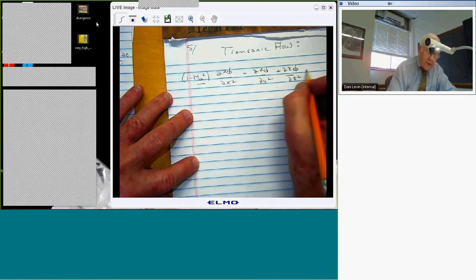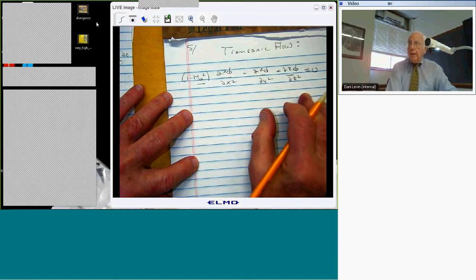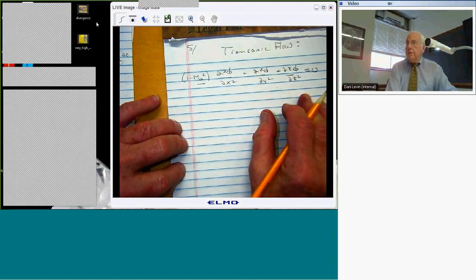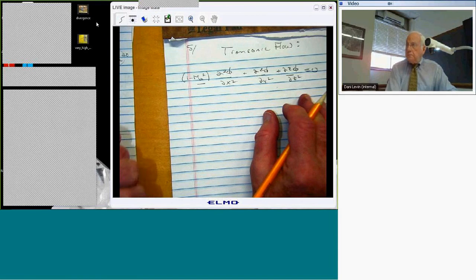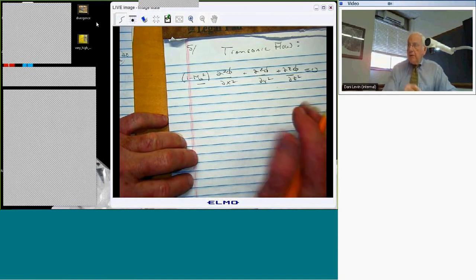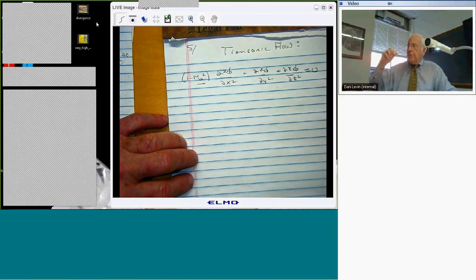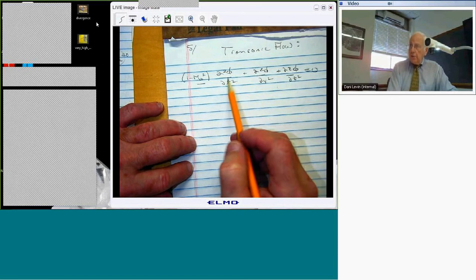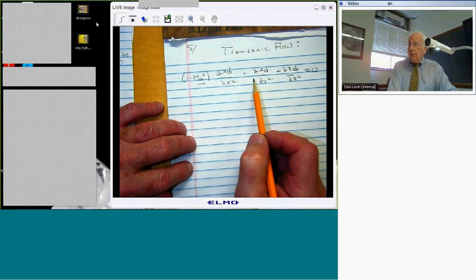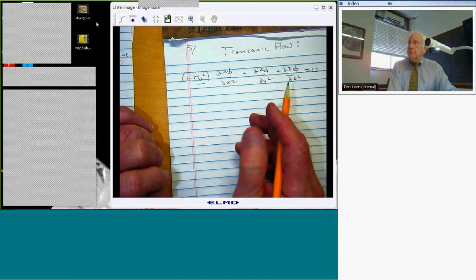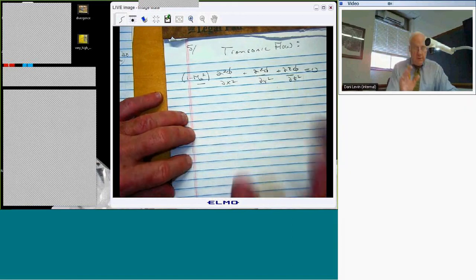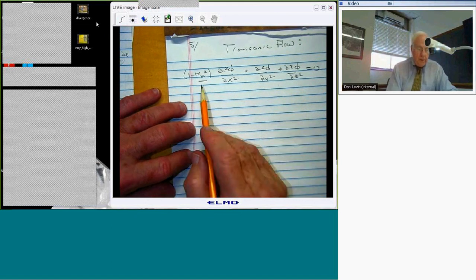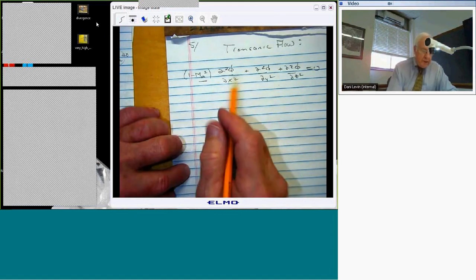This basic theory breaks down more readily in steady flow than it does in unsteady flow. If you are thinking of the body oscillating with a certain frequency, if the frequency is very high, then some of the difficulties associated with the transition from subsonic to supersonic through the transonic regime actually go away, or are less prominent. Okay, you don't know that, but for the moment, take my word for it. So the steady flow case is the hard case in that sense.